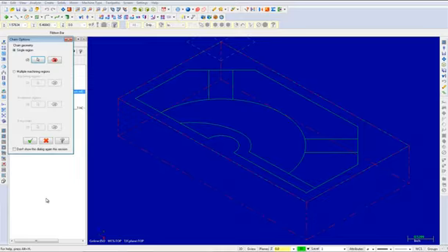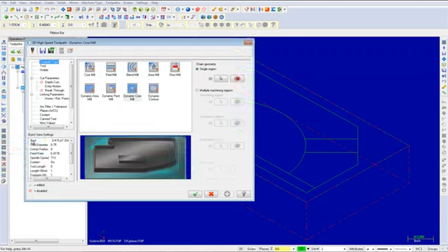Again, select the OK button to exit the Chain Options dialog box. In the Toolpath Type page, Dynamic Core Mill should already be selected. We will now choose a 1/2 inch flat end mill from the library and set the tool parameters. From the Tree View list, choose Tool.